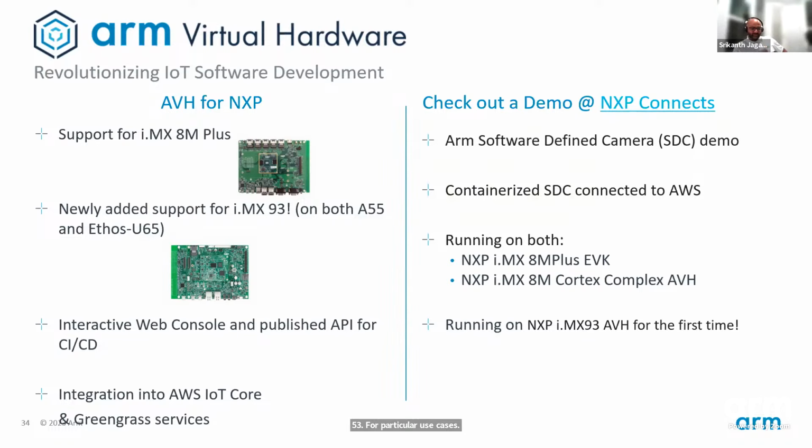Sure. Yes, Toby. Krishna, definitely, the EVK has power measurement capability. It has power measurement ICs on the board, and you would be able to measure the power on each of the power rails going into the i.MX 93 from the PMIC chip. So that's the first answer.